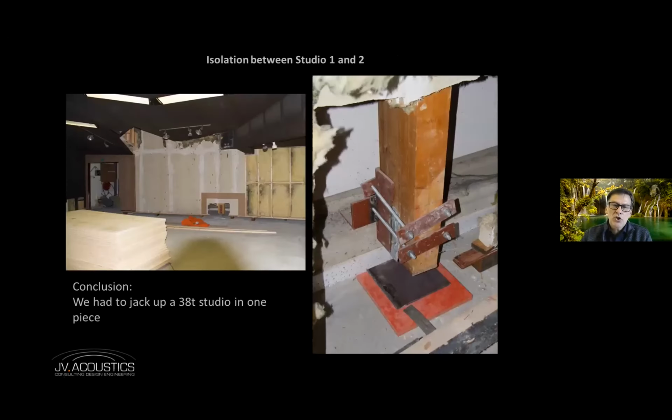So we had to check up the middle studio, the room within a room construction with altogether 38 tons. We had to check it up, put a new lower level footing in, and prepare a decoupling system.